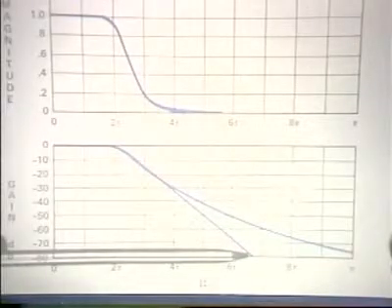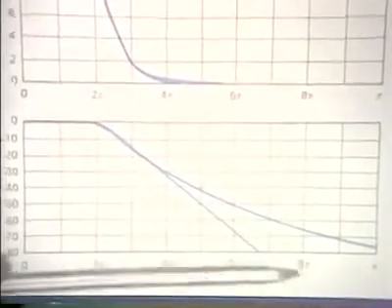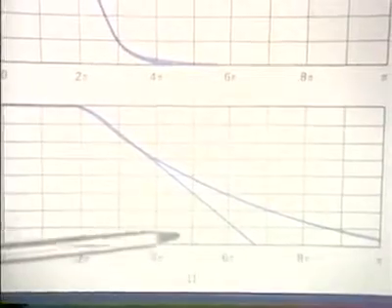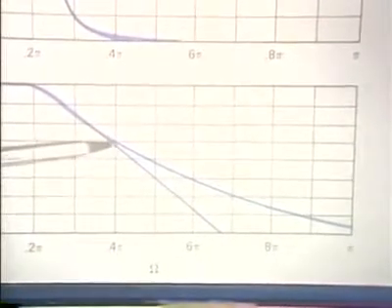So in fact, as we look out along this frequency axis, we're seeing higher and higher and higher frequencies in the continuous time filter. By the time we get to pi, we should in fact be in the continuous time filter equivalently off to infinity, which sounds like a pretty uncomfortable place to be.